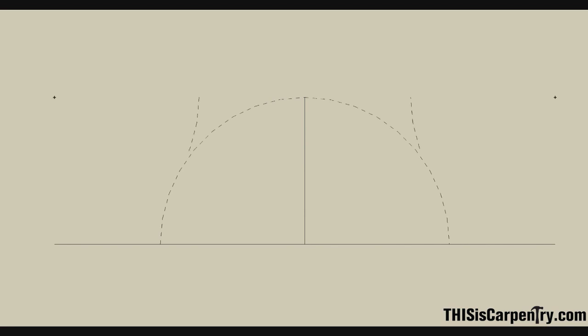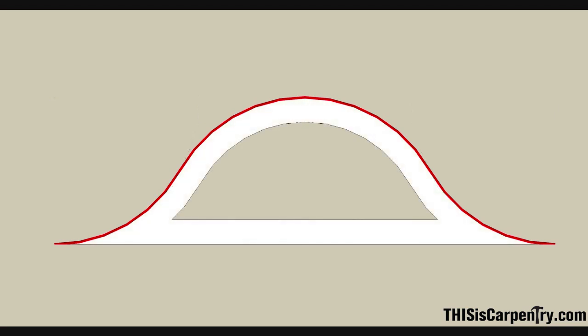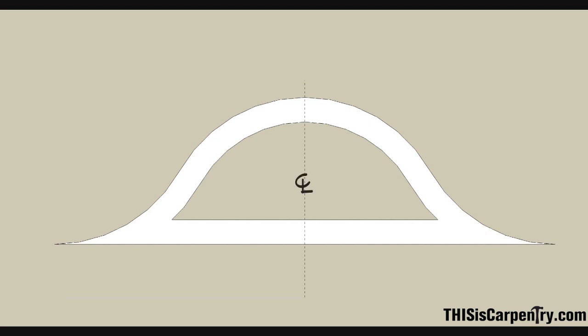3 tangent arcs are then drawn to define the bell curve shape of the dormer's roof. This provides the starting point for drawing the dormer's primary rafter. The next step is to create storyboards that will allow us to transform information to other drawings and plot important points. Since the shape of this dormer is symmetrical, we can find the center line and simply use half the width for the first storyboard.